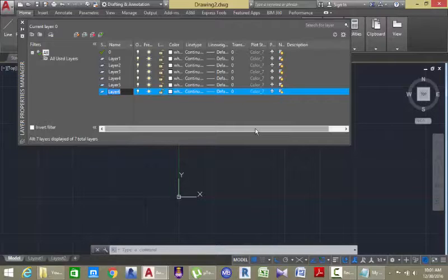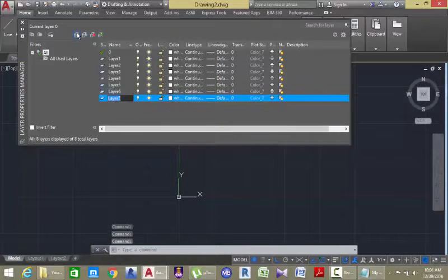So if you put some of the lines in different layers, that can help you to freeze the lines that you don't want to use at the moment. Then when you're done, you take all your objects and put them into a single layer. So now let's create these 6 layers as temporary layers. I'm going to use them during the drawing process when necessary. Then we're going to create 1 more, which we can name edge.